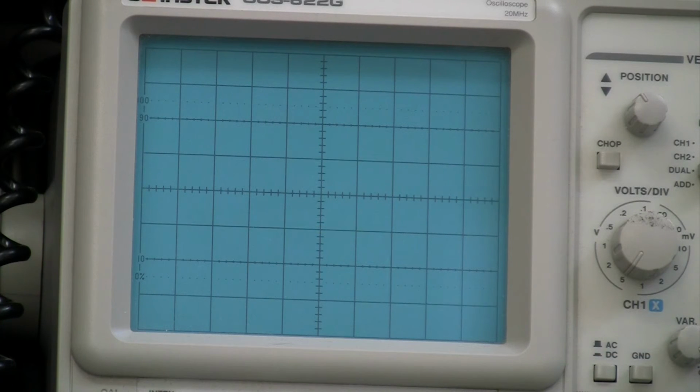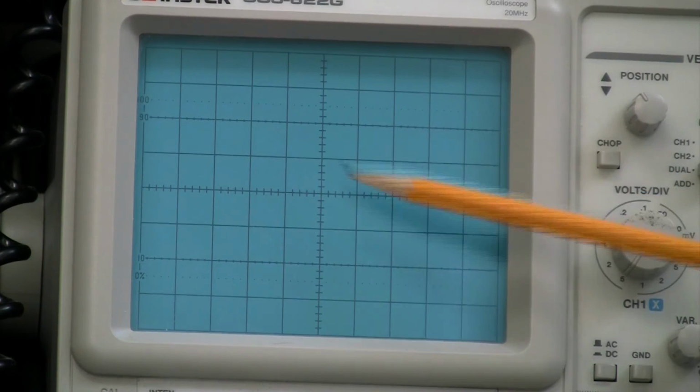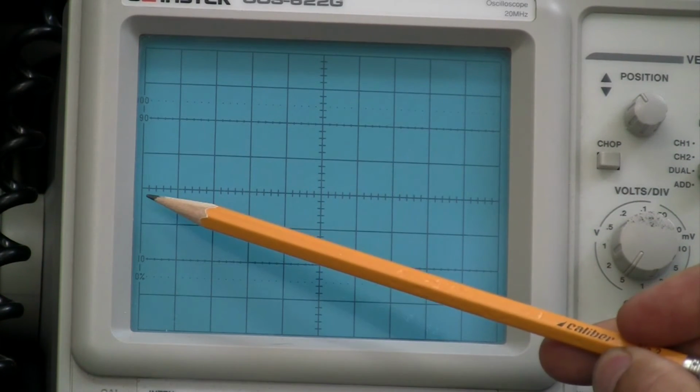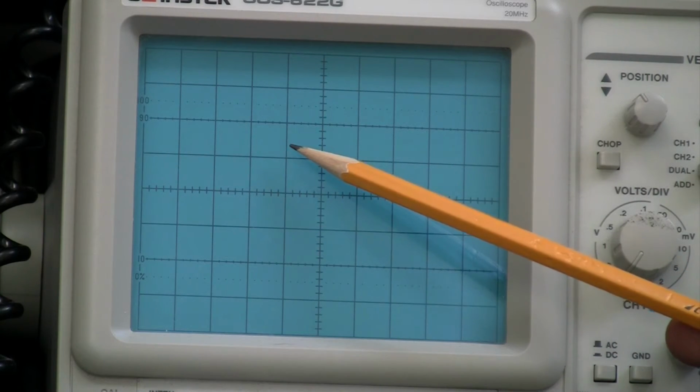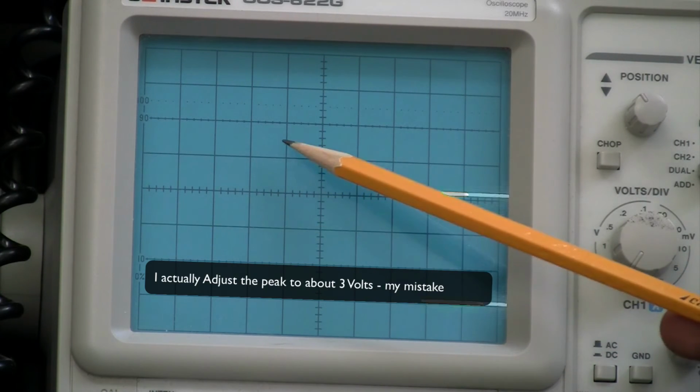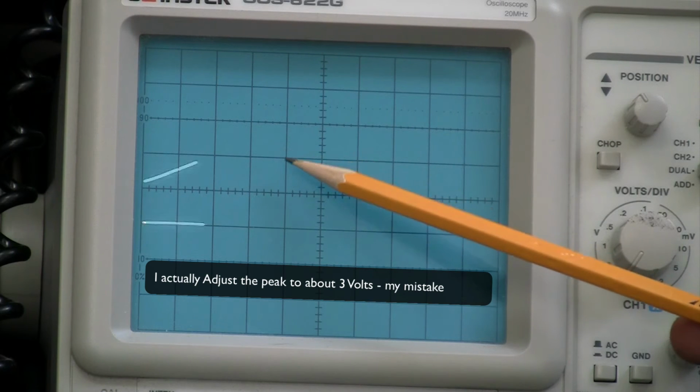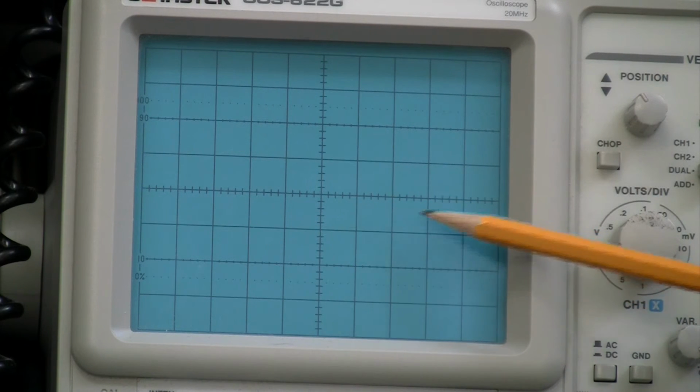If I decrease the control input, the gain comes down, so I turn the gain knob back up. What I'm trying to achieve is a fairly straight line for the attack segment. I'm probably going a little too far there, so I'll back it up. This is just the tweaking phase right now. And I'll say I'm fairly happy right about there. So what I've achieved now is this attack phase, starting at the beginning. It's almost a straight line, goes right up to 5 volts, with a little bit of curvature at the top. The decay starts here, then sustain, and then release.